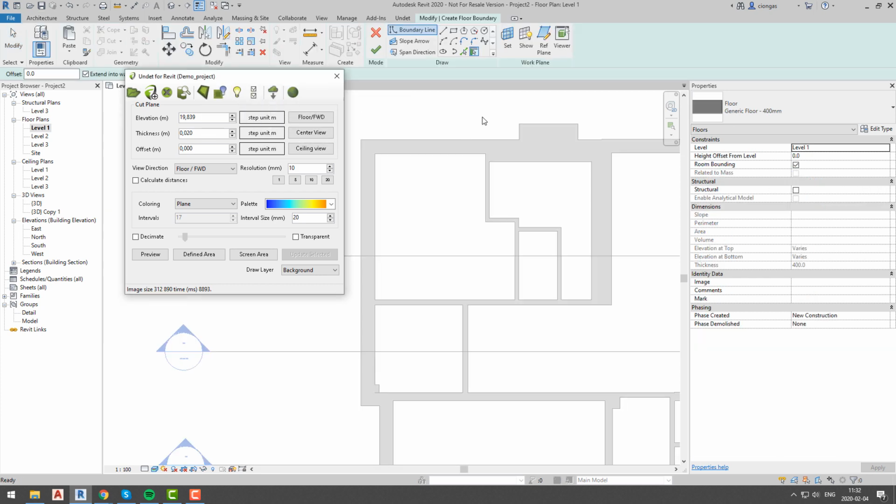Floor modeling can be done in two ways. First, we can manually draw floor for each room like we are doing right now and follow same workflow as we just did for adjusting ceiling level. Another way is to create ceiling for whole level at once, and keep it as span. It all depends on how detailed your model will be.